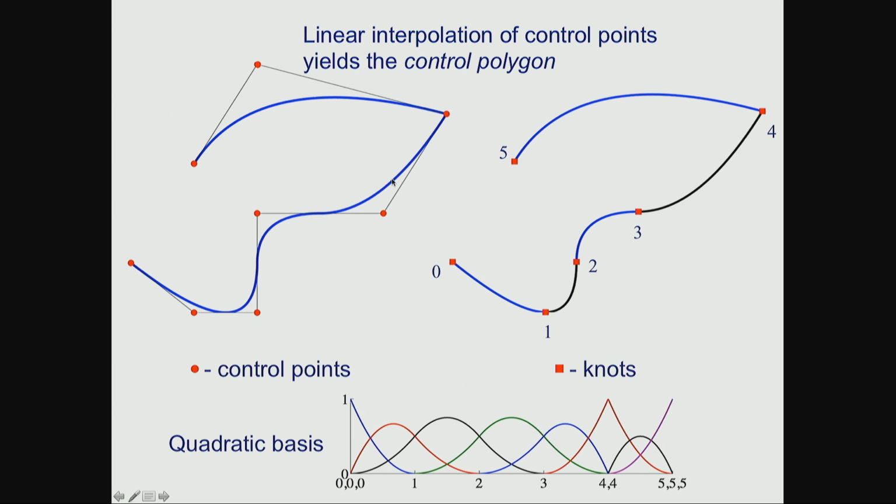Now, this is the finite element point of view of the design. You can deconstruct the design by way of Bezier extraction into Bezier elements, and they play the role of elements in isogeometric analysis. And in fact, you can do everything that you usually do once you understand the concept of Bezier extraction. There's an extraction operator that facilitates this. It's just a matrix. So you have a finite element point of view of design, and you also have the classical design point of view, which utilizes, let's say, the global basis functions here. Here you'd be dealing with polynomials on each individual element.